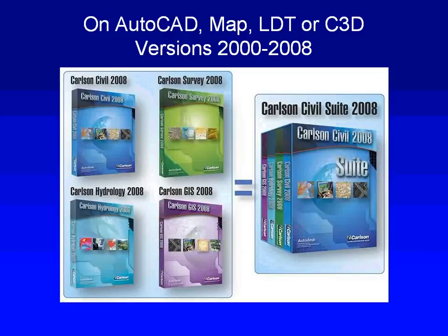And if you plug into Civil 3D or install it on top of Civil 3D, a similar situation. Carlson is using the AutoCAD engine, and Map is fully available. But Carlson commands are not going to be creating Civil 3D objects. However, all the Civil 3D menus and the tool space are all available, and you can just switch over there and do whatever work you want to do. And actually, basically LandXML while you're live on top of the software. So some interesting possibilities. I just wanted to be clear on that, and hopefully that makes sense.